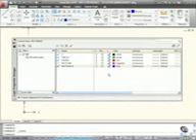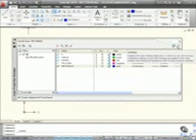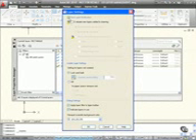Now you'll see we've got various layers there with various colors, various names. What I want to do is change some of the settings. So I go now to this little spanner here, or wrench as it's called in the United States. Now you'll notice I've got new layer notification here. I'm going to switch that on, and I'm going to ask AutoCAD to evaluate any new layers added to the drawing. And I'm going to ask it to evaluate all new layers. Then it will notify me when those new layers are present.